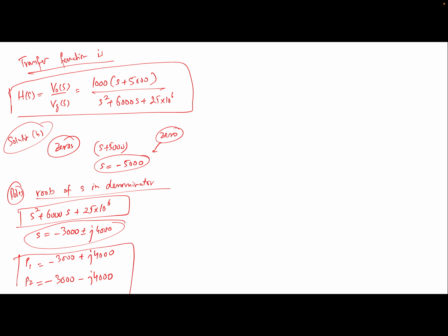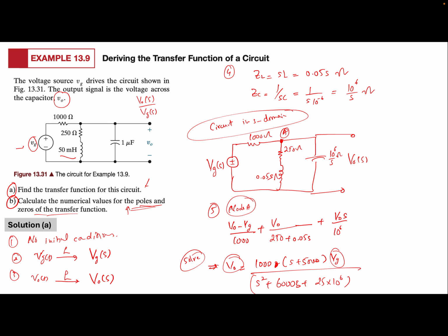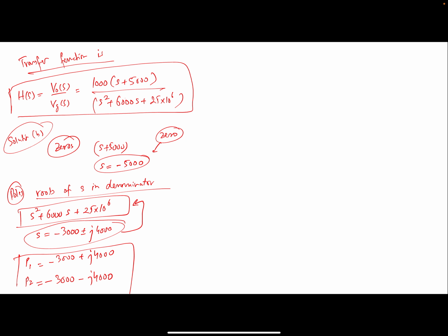Again, these are the roots of the denominator of the transfer function. Again, very simple to calculate transfer functions. You have already learned enough Laplace transform to solve for this. So the transfer function is a new concept, but you are practically solving the same circuits. Converting the time domain circuit into an S domain, we have done that enough times. Then just writing an equation in a way that you are defining a particular output as a ratio of a particular input, it becomes a transfer function. Cool. And then the rest of the whole analysis is pretty much the same.